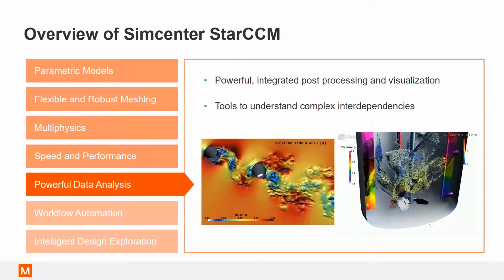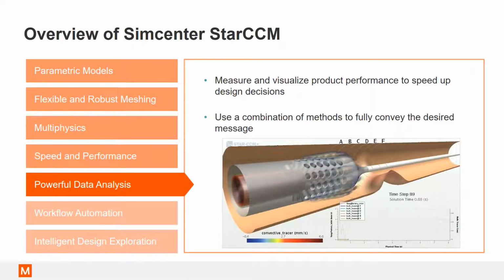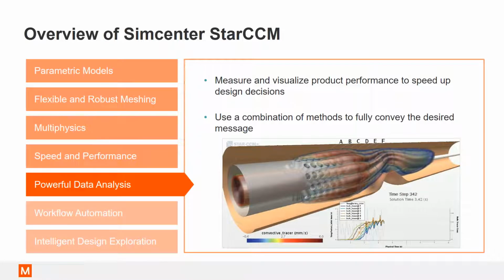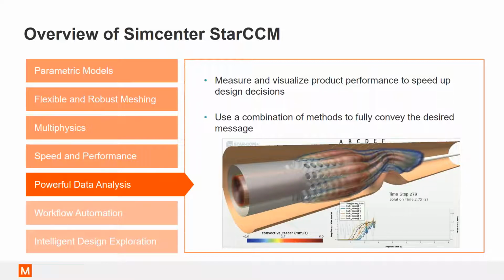But one of the key features with Star CCM Plus is the ability to visualize the results live while the solution is running. This is great when trying to understand the flow behavior, but at the same time, it's also good in just making sure that all your boundary conditions are appropriately set up and not having to wait for hours to look at the results to understand those errors.